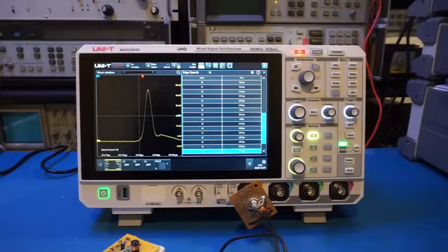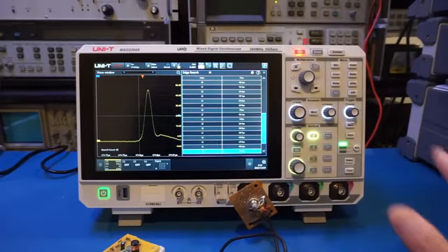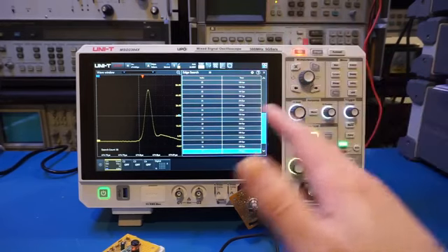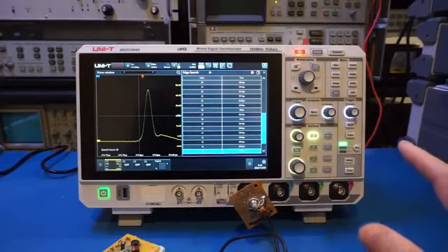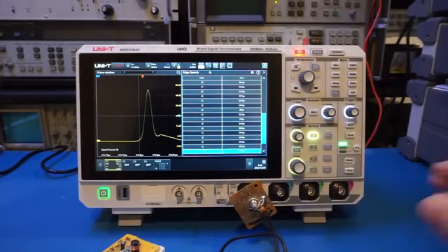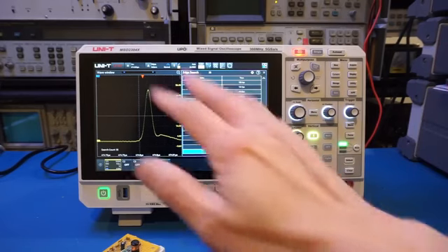Now, one of the challenges of capturing this sparsely occurring signal is that once the scope is triggered, it will continue to sample the channel until the sample memory has been filled. The problem is the signal of interest could be very short, and the repetition interval could be very long. So if you're doing a single shot, you are probably not going to capture many instances of the signal of interest, even with a large sample memory. And this is actually what is happening here.